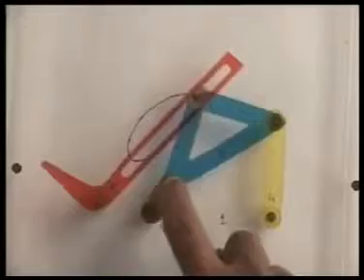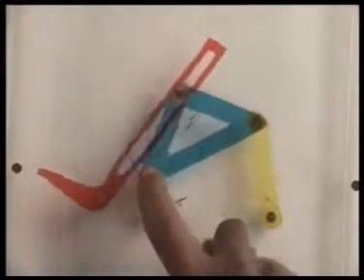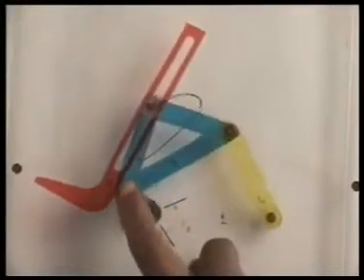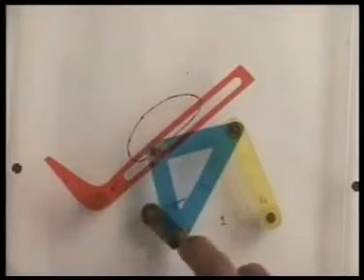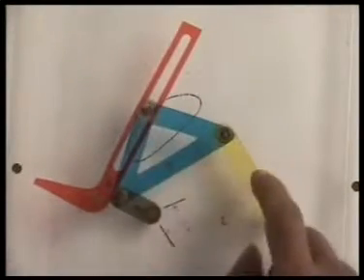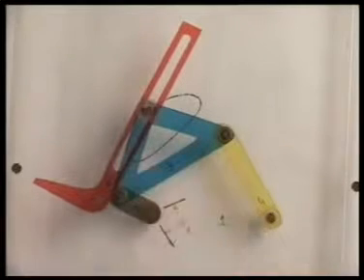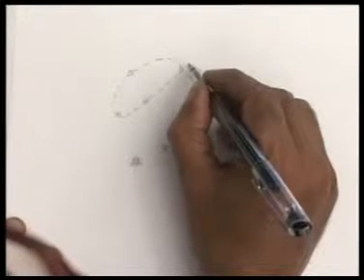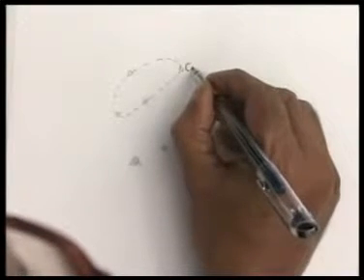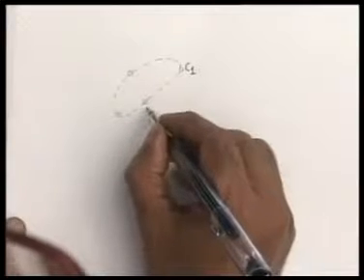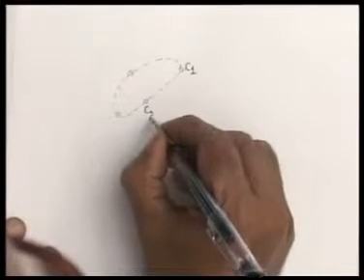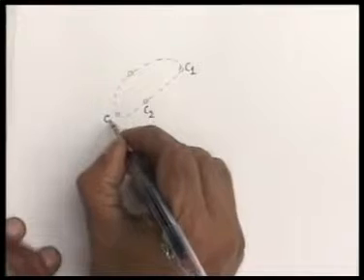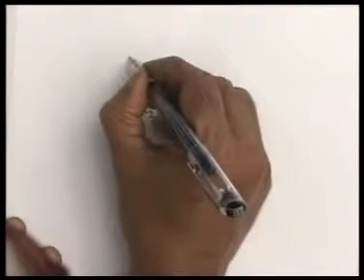Our job is to design these linkages using the method of point position reduction. First we shall design a 4-link mechanism with 4 points on this coupler curve, namely C1, C2, C3, C4. Suppose we want to synthesize this coupler curve by allowing the coupler point to pass through these 4 positions, namely C1, C2, C3 and C4.